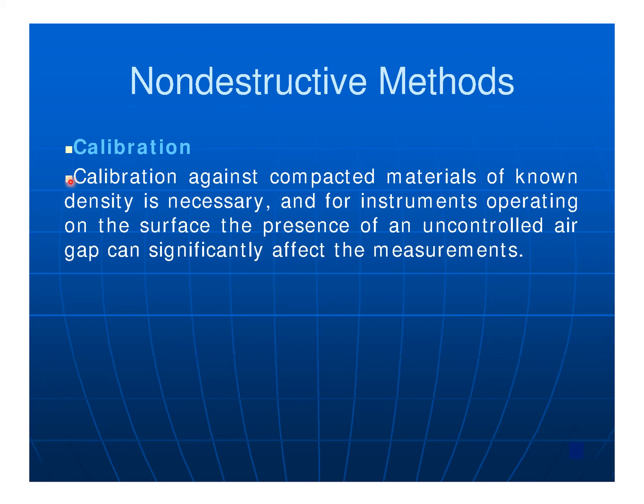Calibration against a compacted material of known density is necessary, and for instruments operating on the surface, the presence of an uncontrolled air gap can significantly affect the measurements of the nuclear density meter.